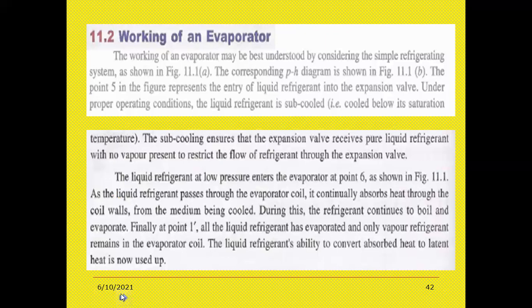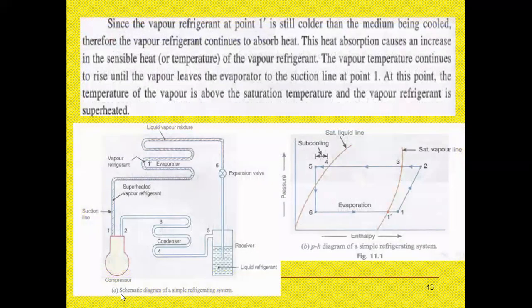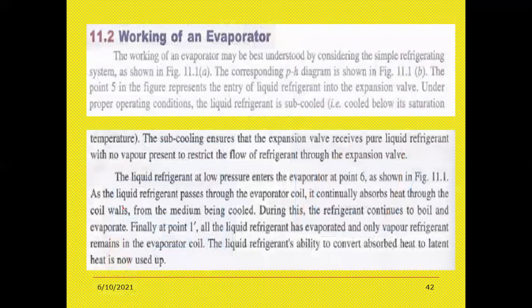See the figure 11.1. The liquid-vapor mixture from the expansion valve goes into the tubes of the evaporator, and from the evaporator it leaves as superheated vapor refrigerant.